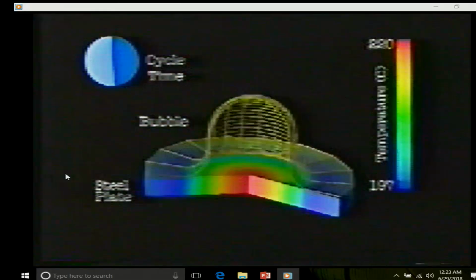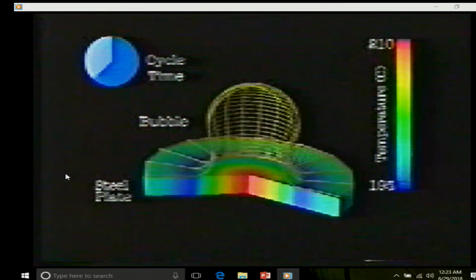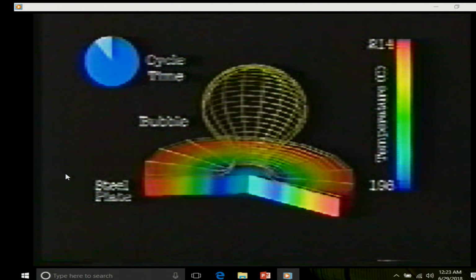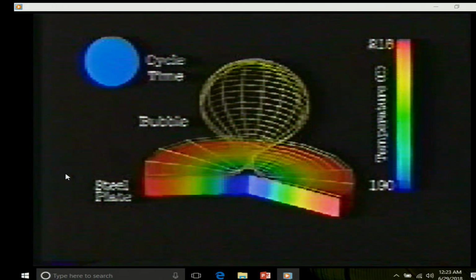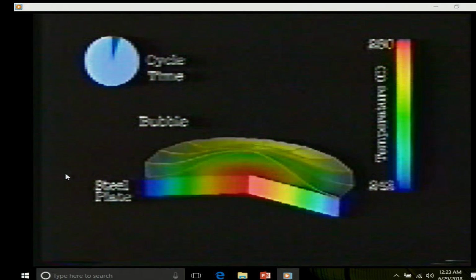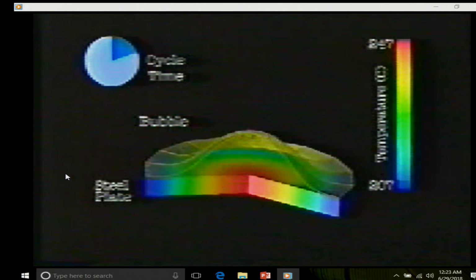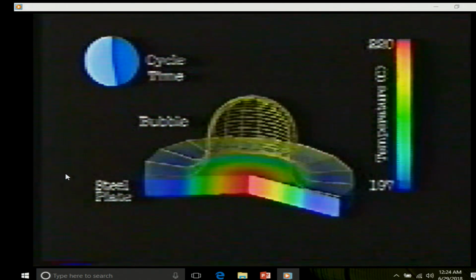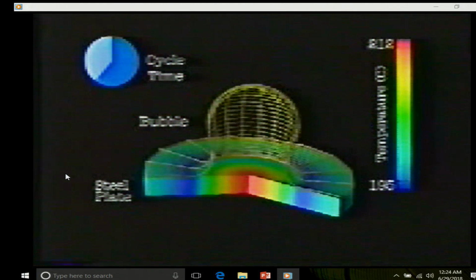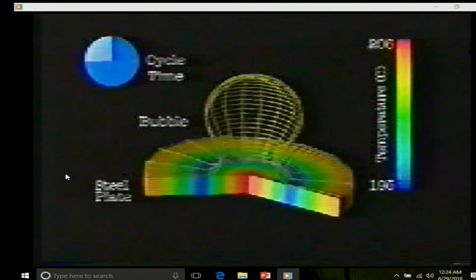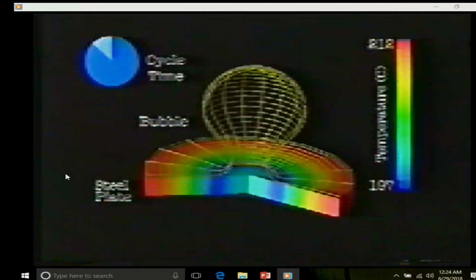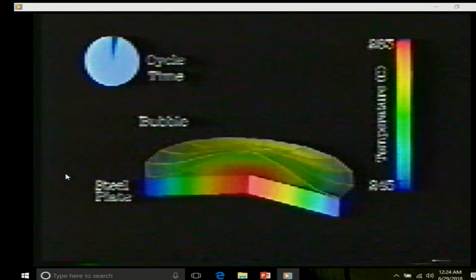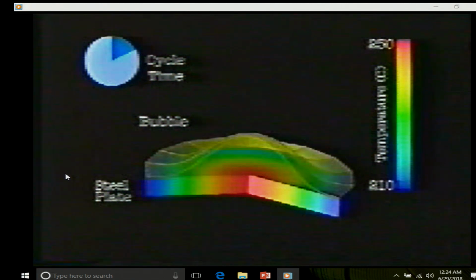So, if you notice, it starts in the beginning with just a simple vapor film thickness, and the whole thing develops on its own without making any assumption for shape. We are not imposing any shape on the bubble; it is choosing the shape based on the Navier-Stokes equation and how the pressure field evolves with time. So, this is the first time in the literature that we could show how a cold spot forms, and that the cold spot forms on the outer edge of the bubble and moves radially inward with time.